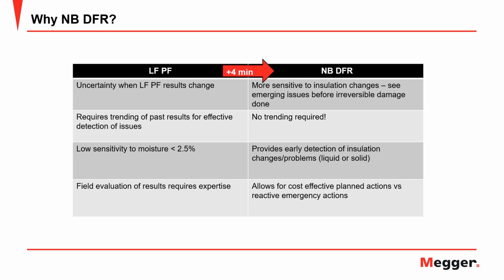Line frequency requires some trending. With narrowband, you will see that our analysis will provide you some values, right? And if later on you would like to do some trending on, say, 1 hertz or 2 hertz or 10 hertz, you can also do that because you have the information anyway in your narrowband testing.